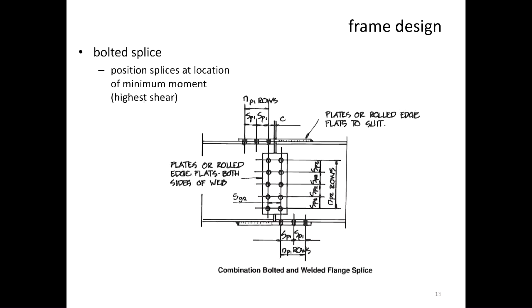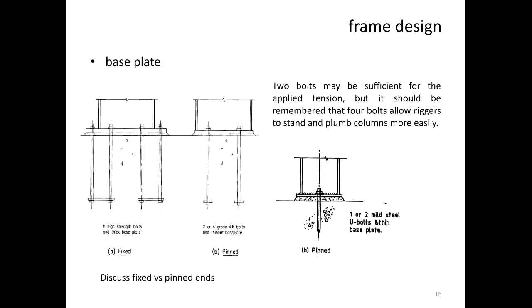So generally, when you have a bolted splice, it's much easier if it's a beam. If you have ways and means to make constructability or buildability easier, it's always better to do that. That is why in this case, as I explained before, we have the plate welded to one side, so when you put the other beam, this plate picks up the beam and you can bolt the connection easier. This is just thinking about how it's going to be constructed, which not all engineers generally do.